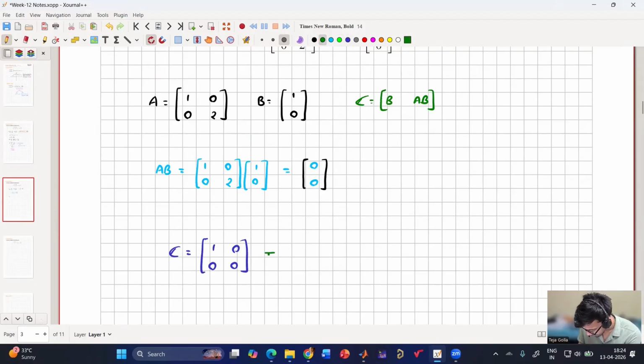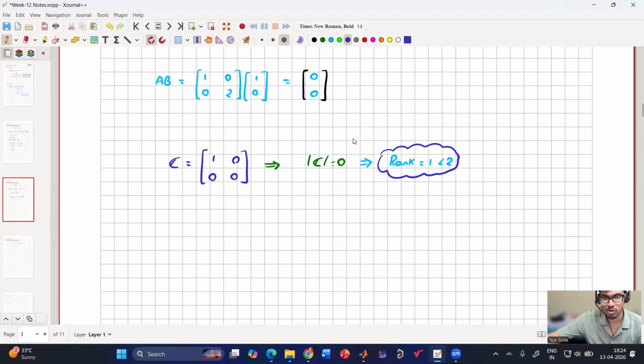So now we can see the determinant of C is 0, right? Determinant of C is 0, which means rank is not 2. But is there any non-zero element in the matrix? Yes, so 1. So the rank is 1 and not 2. So that means in this case, rank is 1, which is less than 2, which means it is not fully controllable. So all the states are not controllable. Some are uncontrollable.